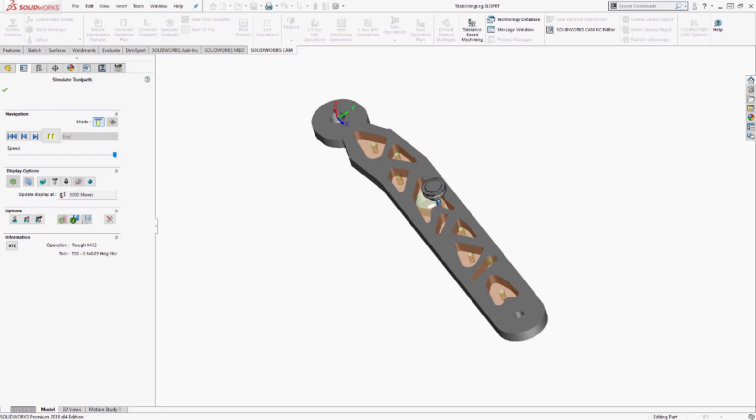And actually, funny story, when I first created this, he came back to me and he told me, yeah, there's some fillets in here which are too small. I would have to do additional operations for that, so could you increase the size of that, right? And because I was inside the SOLIDWORKS interface, I could go ahead and do that to then create a final design which he could machine in just one operation, right? So that's where we are with this.